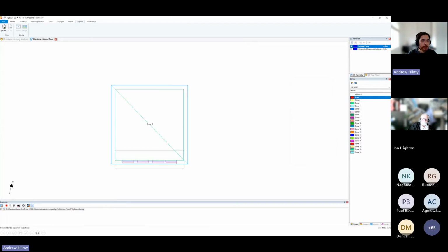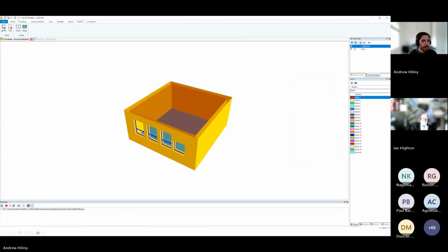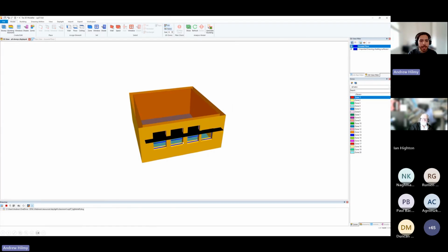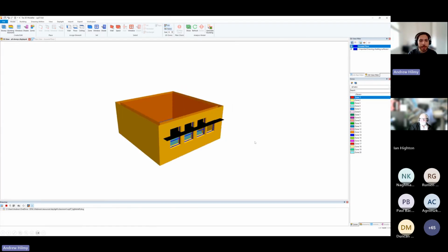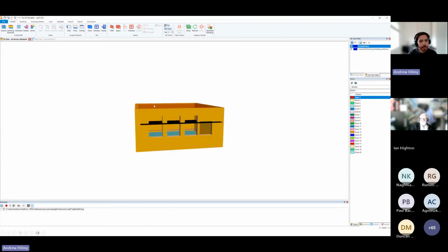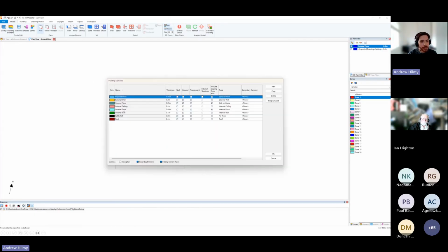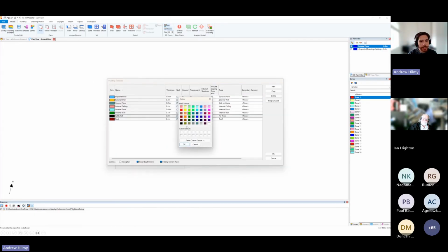By default, I need to refresh the analysis view. That will import the layer there. It will come through as a separate story, all the geometry on that. And it comes through as black because that's the color that was in the DXF file. But if I wanted to, I could change the property of that light shelf. I could make the color green, for example.